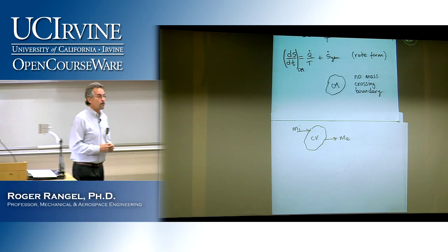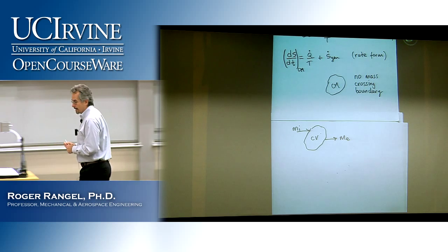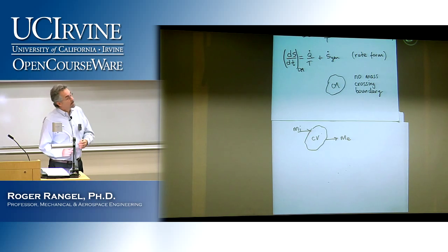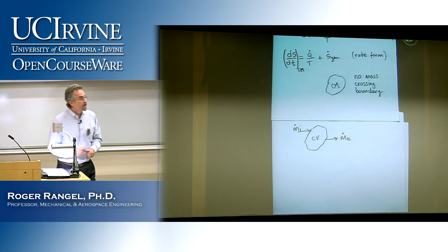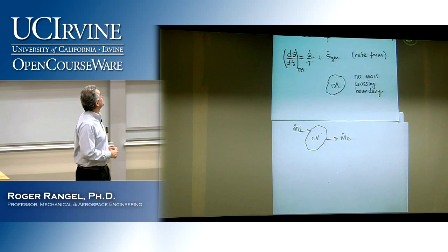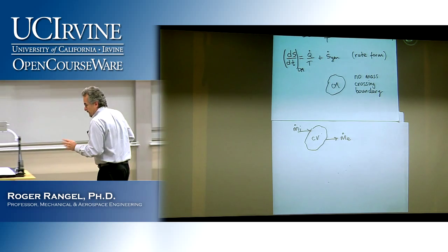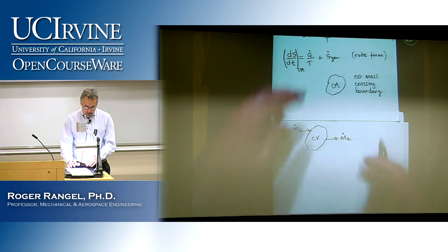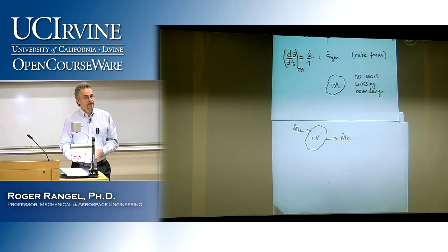So it's very easy then. How do I find the rate at which entropy is coming in with that mass? If I have them in terms of rates, which is the way I have written the equation, you may want to add dots there, because we're having it in terms of rates. We have a certain amount of kilograms per second coming in, a certain amount of kilograms per second going out. Then all we need to do to this equation is add two terms on the right-hand side.